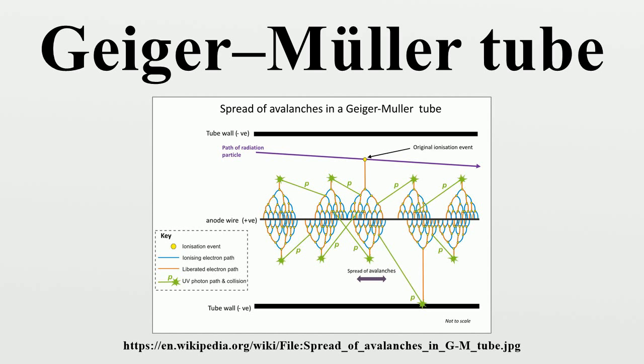Fold back. One consequence of the dead time effect is the possibility of a high count rate continually triggering the tube before the recovery time has elapsed. This may produce pulses too small for the counting electronics to detect and lead to the very undesirable situation whereby a GM counter in a very high radiation field is falsely indicating a low level. This phenomenon is known as fold back.